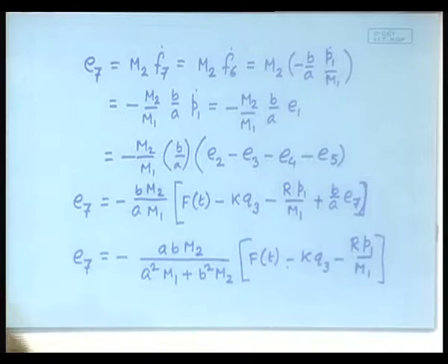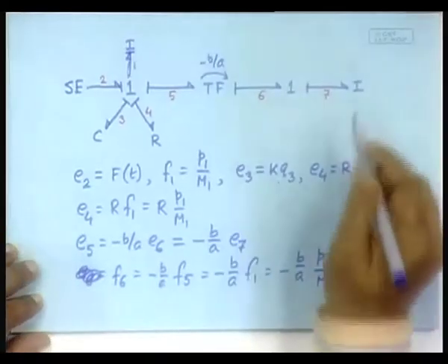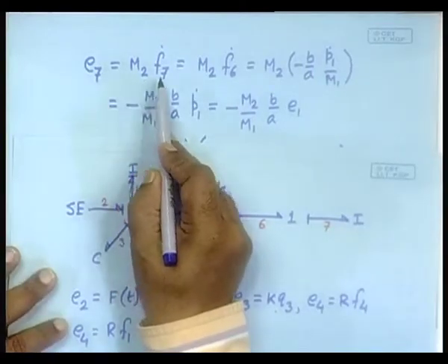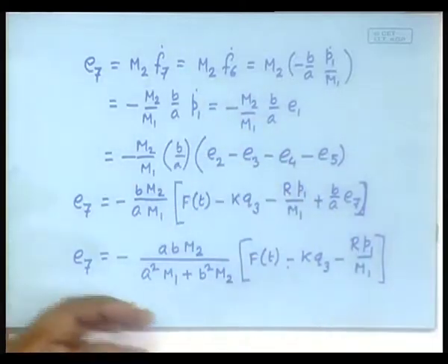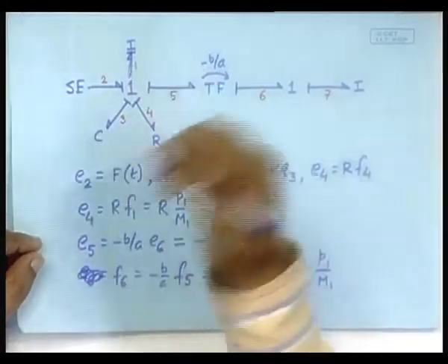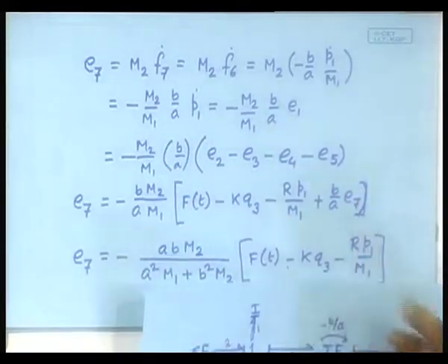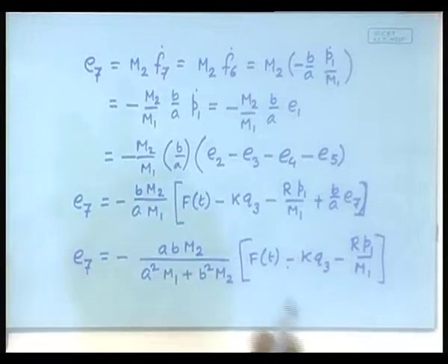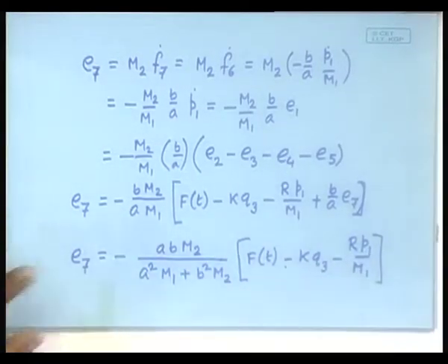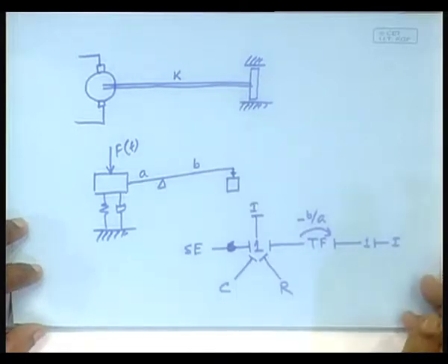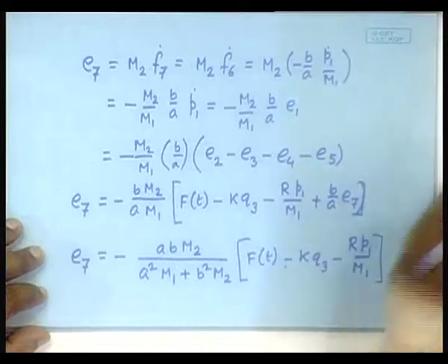So, there was no great conceptual difficulty. The only thing that we did was we asked the question related to this element and then linked it with the character of this element by the force equals mass into acceleration equation. Then we went along the bond graph to find out where this information comes from. Finally, we reached a place where we know the variable, that is P1 dot. We made it E1 and then we could substitute the rest, but such a system always would lead to the same term appearing in the left as well as in the right, and then there has to be a bit of algebraic manipulation involved in order to calculate this variable, but it is doable, that is the point. So, even if you have the difficulty, it is not always desirable or necessary to put in additional dummy variables, because those additional variables would in many cases give rise to a lot of problems in actual computation.